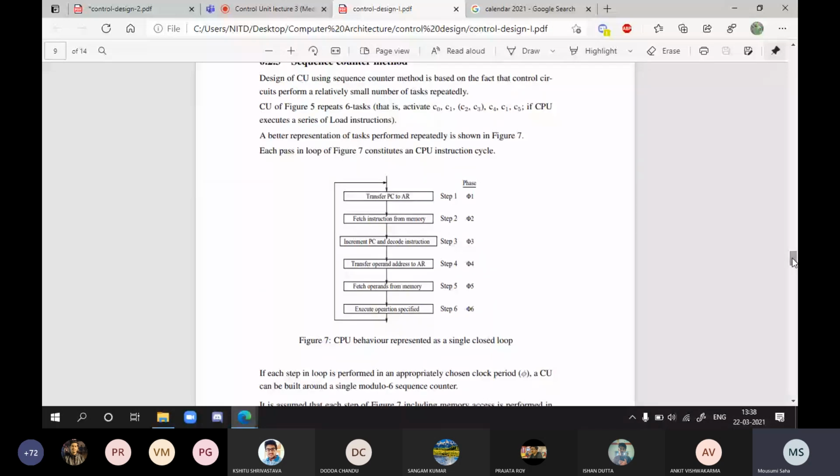For example, memory read operation and memory write operation. Fetch is the term we always use for reading the opcode from memory, so fetch is also a memory read operation. The processor can read memory to read the opcode, sometimes the address, sometimes the data.